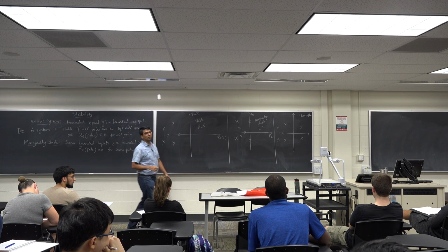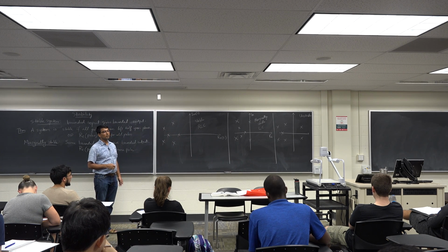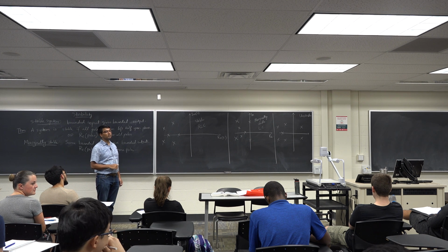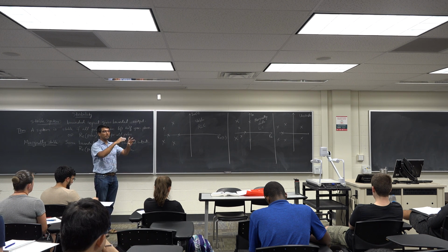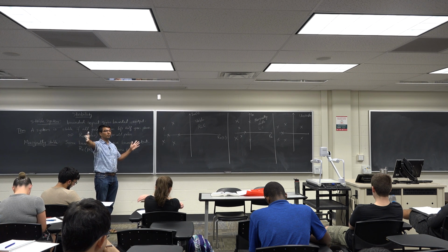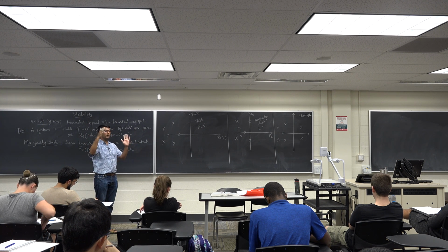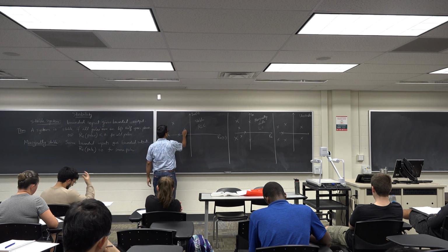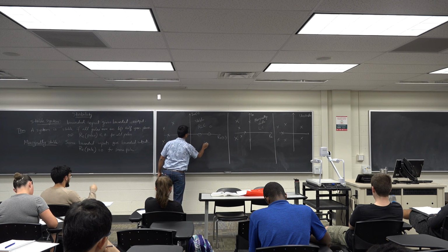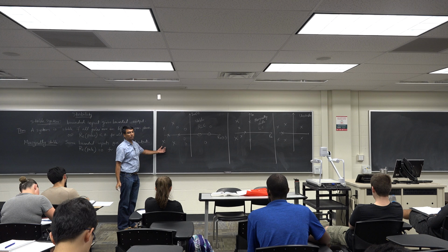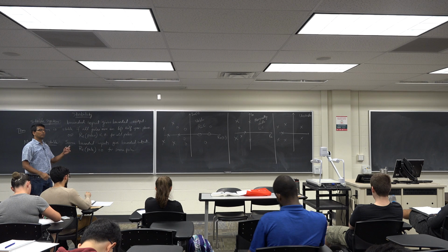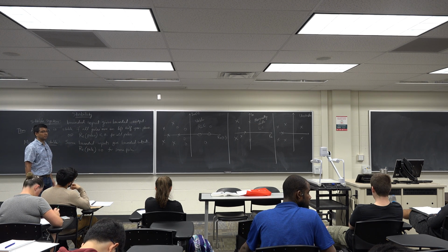Yes. Say you have a big block diagram, so not each individual block needs to be stable. Yes, that block could be unstable, but if you reduce it down to one block, that's right, you can tell the entire system. Once you put the controller in, do all the negative, positive manipulation, once you get the final transfer function from input to output, that should have a pole zero diagram that looks like this. Again, zeros, I don't care. Zeros could be anywhere. I'm not particularly worried about them. But poles have to be in the negative real part. If you have multiple inputs, then the transfer function corresponding to each input has to be like that.